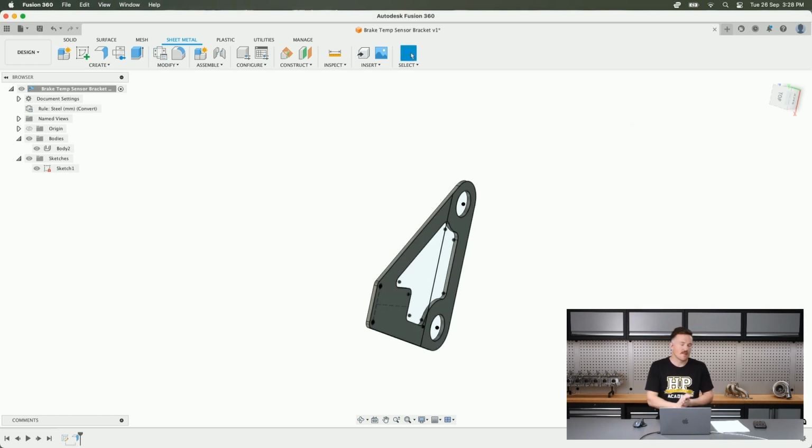And the importance of our sheet metal rules, these are quite critical to modeling sheet metal parts in Fusion 360. And what it does is it basically applies these rules automatically to the part depending on its material and its thickness, and it helps to automatically apply DFM considerations. So that's design for manufacture considerations, like minimum bend radius and things like bend reliefs, so little cutouts, to basically ensure that we don't design something that when we go to make it, when we go to bend the part, is going to rip, tear or fracture and basically be a weak part.